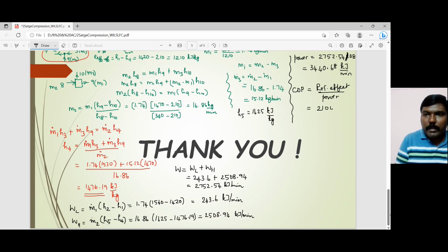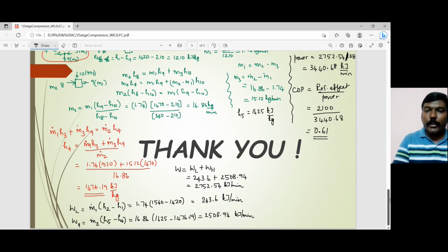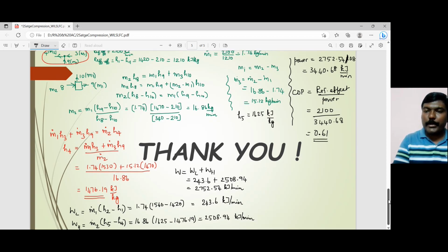Refrigeration effect is 2100 and this guy is 3440.68. 2100 divided by 3440.68, so that is 0.61. So this is the COP. Okay, so that's all we have in this particular video lecture, and in the next video we will talk about three-stage compression. Thank you.